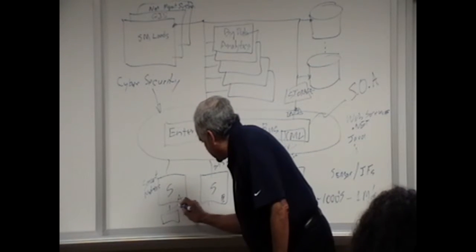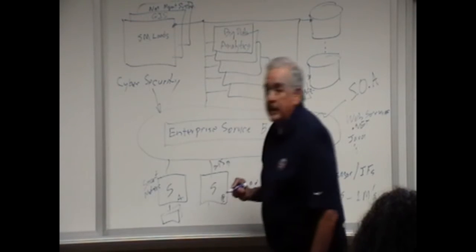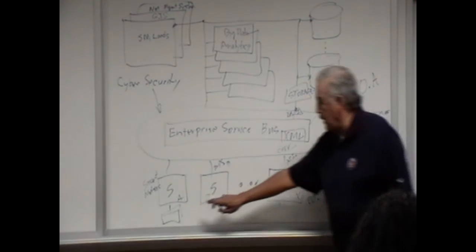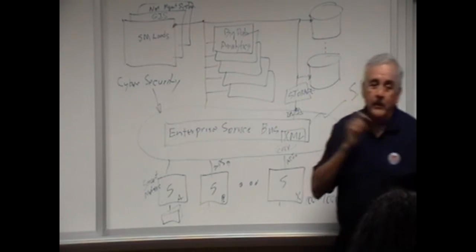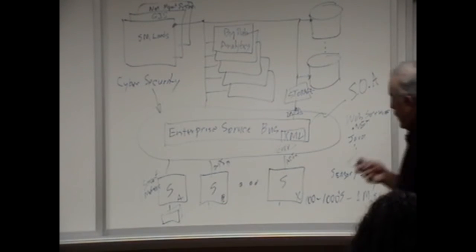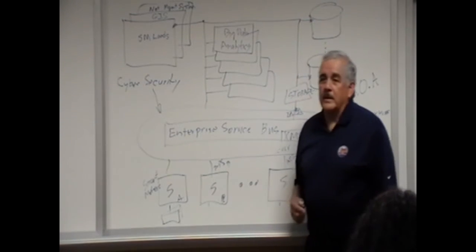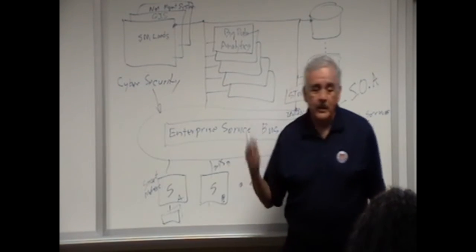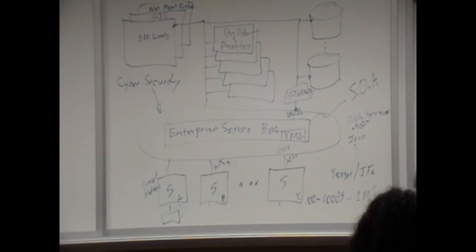You're measuring consumption on that building. We have a smart meter right now in the library, and it measures the energy consumption, the amps and volts, the kilowatt hours that's used every 15 minutes. We poll that meter every 15 minutes and collect data on it.